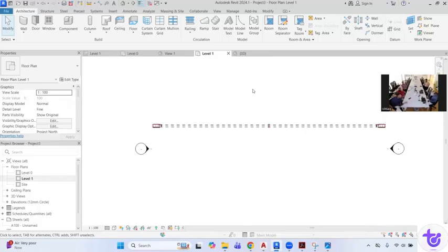Yes, you are absolutely right. But there are certain constraints with the Revit template itself. It actually works well with the cut plane and the top. The view range will work for most of the building elements. But if you notice any in-place family, it will not fall under the view range category, because if any part of the in-place family falls within the cut plane, it will show the entire family.